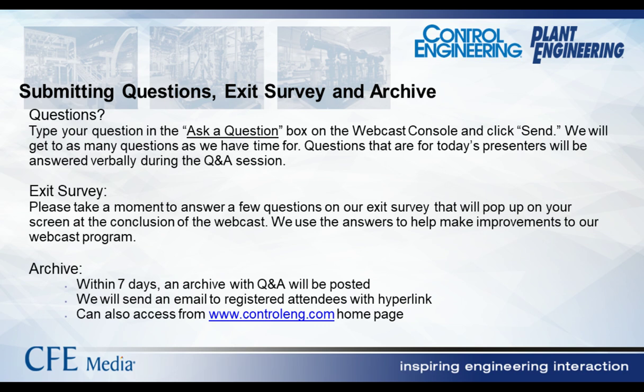A great example is developing a machine vision application for a part, and the finish of the part is wrong. So we develop all of our solution around that test piece, only to find out that the part is really shiny and not dull in the production environment. So ensure that you get the right parts during testing and that the right testing requirements are defined.